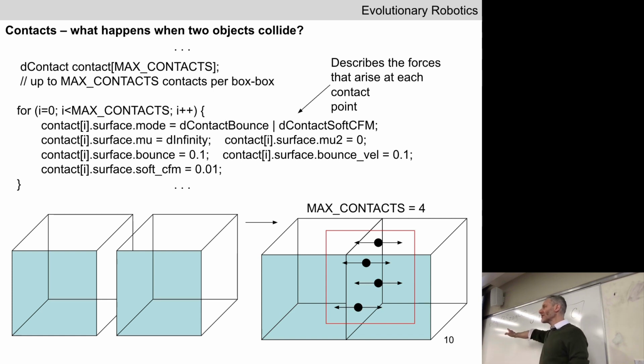Remember that regardless of the physics engine you're using, in a physics engine, time moves forward in discrete moments. And that discrete updating of time has huge repercussions for everything that happens in a physics engine, including collisions. We've got two objects that are moving towards one another, but the positions of those two pieces are teleporting actually a short distance during each time step.